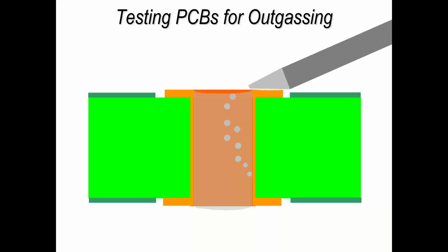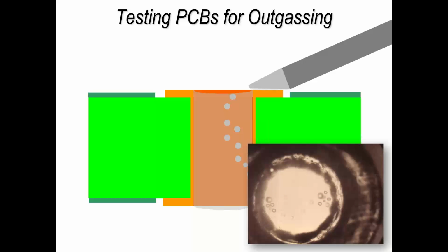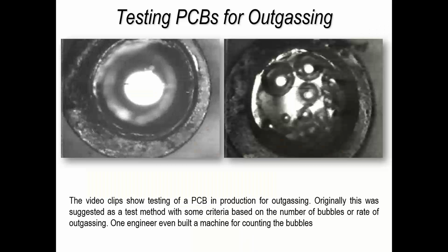And because we're doing this in this way, we could reuse the board if we take great care when we're doing the heating operation with the soldering iron, because you can just clean the oil off. But it's a great way of looking down the plated through hole, as you see here, this sky view, and you can see the little bubbles.